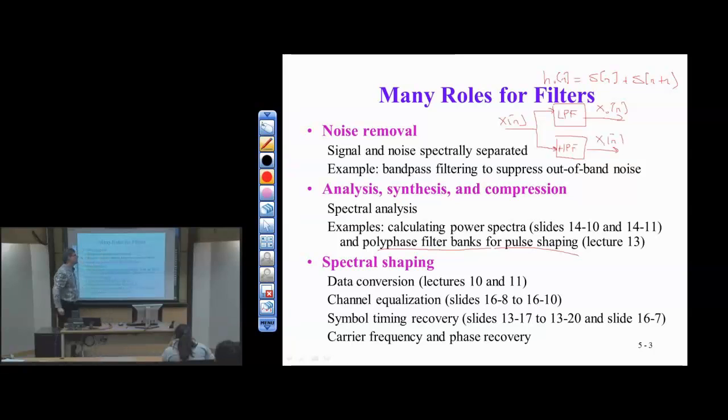In terms of input-output relationship, it's going to average the current input and the previous input value. High-pass filter, what's an example of a high-pass filter? Differentiator? First order, the equivalent of first-order difference, or first-order differentiation, which we would call first-order difference. What's that impulse response look like?